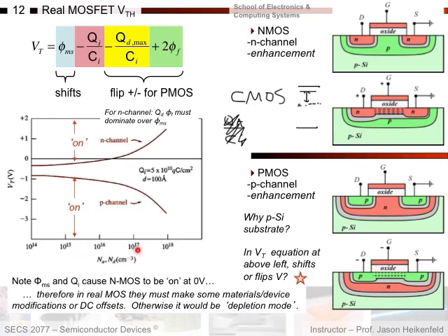You can see that as you increase doping level, the threshold voltage starts to increase. And so what that tells me is that these things, which increase your required amount of voltage, remember, this is the price we have to pay, must dominate over this, because we said that this became more negative as you increased your doping level in the substrate. These ones must dominate because they're positive and they increase as you increase doping level. More atoms to uncover, more Fermi level shift that's necessary. And so you can see your threshold voltage is increasing, so these terms must dominate over this in terms of the effect of increasing doping.